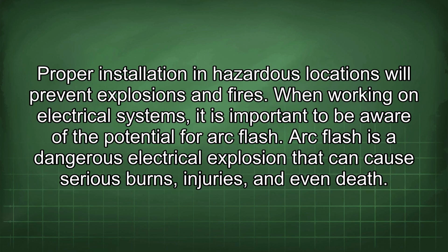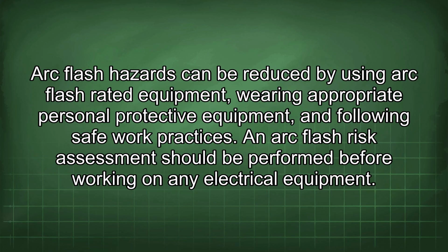Proper installation in hazardous locations will prevent explosions and fires. When working on electrical systems, it is important to be aware of the potential for arc flash. Arc flash is a dangerous electrical explosion that can cause serious burns, injuries, and even death. Arc flash hazards can be reduced by using arc flash rated equipment, wearing appropriate personal protective equipment, and following safe work practices. An arc flash risk assessment should be performed before working on any electrical equipment.